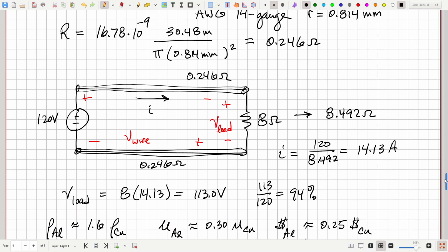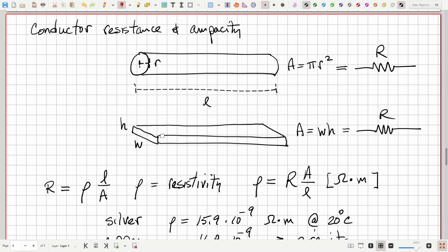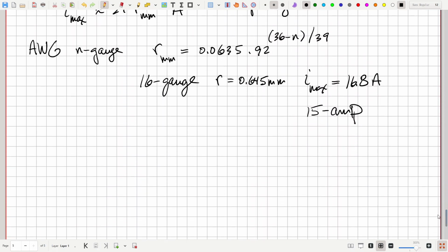All right, now, using this idea, with this kind of rectangular geometry, we can see how actual circuit resistors are built. We start off with an insulating, cylindrical core, usually made out of some kind of ceramic. And then on top of that, we run kind of like a spiraling conductor. This is all one piece. It would go up from behind and then continue around like this.